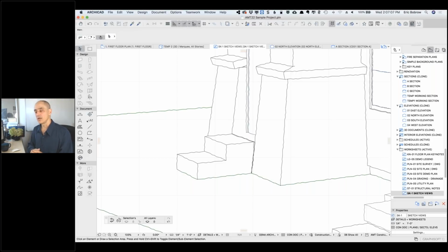So you have to be careful in the sense that if you change something in a view setting or in the model view options or anything, then it will change. Now, what I was doing here, I'm double clicking on a view, it restores things. If you don't redefine the view, but you simply select different model view options or overrides and just say, well, what does it look like if I switch? You're not destroying anything. You're simply saying, right now I want to turn this to a different setting, but you're not changing the view definition or the definitions of the styles.